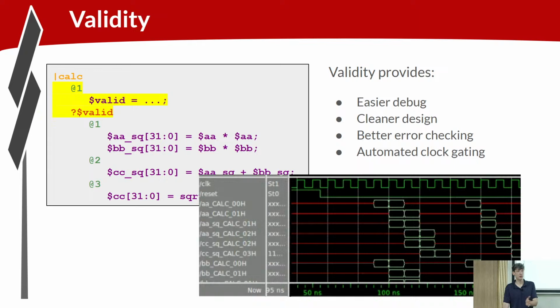Reset should put you into a known state, right? When you power up your circuit, you literally don't have any guarantee as to what the values in the circuit are. You simulate for a while, and that should clear all the don't care state to a known state. So you're verifying that the application of reset is getting you into a known state. And that's what Professor Boku is alluding to.